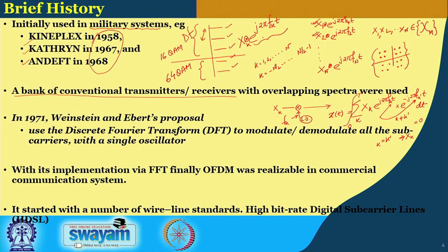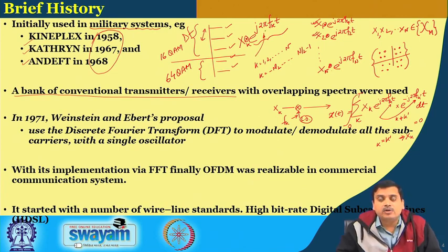Here the weights are drawn from the exponential function, whereas what we discussed there is a more general case, where the codes could be drawn from any function. Hadamard is one particular way of generating orthogonal codes. Here, if we connect to this, we can think of the DFT matrix, which we will see could also act as a generator of codes.